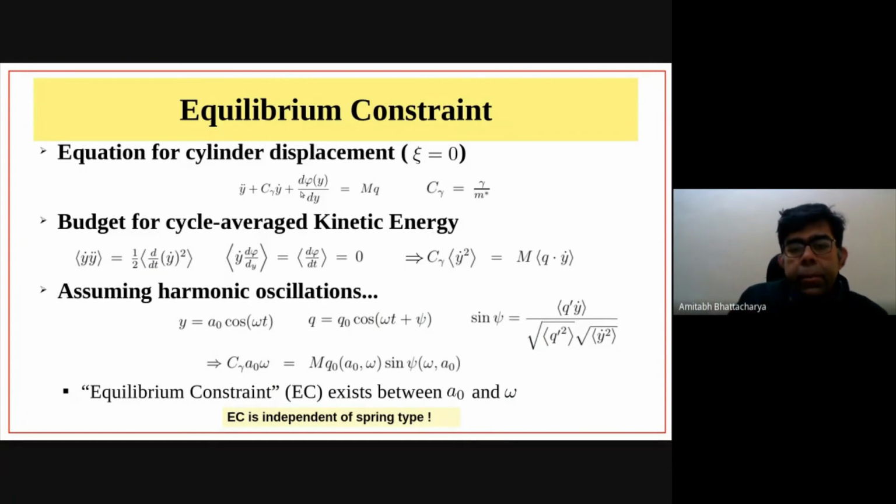Energy can be only created or dissipated by the vortex shedding forces and by the fluid or structure damping. Therefore we only have the net energy dissipation due to the structure or fluid damping balancing out the net energy production due to the vortex shedding forces.